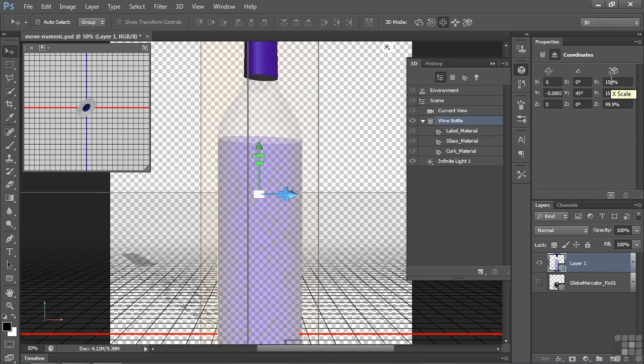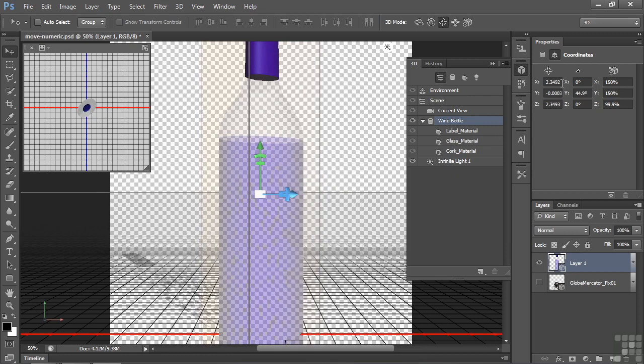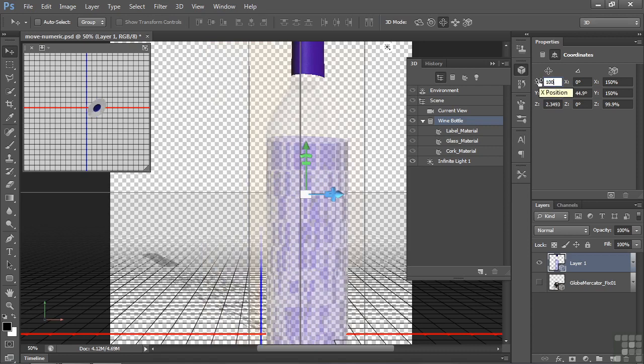If I want to, let's say, change the position, obviously I could change the position just by dragging it around like this, but I can also do it numerically here. Notice how those numbers change there. Let's say I just change the number to something like 100 now. Drag it across there, like so. Type in 100, and notice how it moves, but I do need to lock that number in by pressing Enter, Return, or Tab even. That'll lock it in for us.